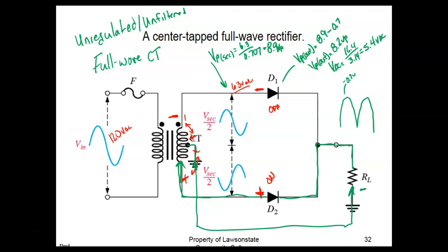So if you ever took an oscilloscope and put it across your battery charger, it's full wave. Now what type of transformer it uses, whether it uses center tap or the other one, probably uses center tap. I think I've torn one apart. In fact, I've had one go out, and one of the diodes actually burned out, and I took it apart, replaced the diode in there, and it worked fine. So I don't know if I still got that one or not, but yeah, battery chargers will do that, if you don't have it connected to the battery.